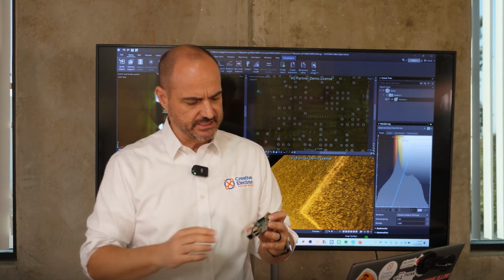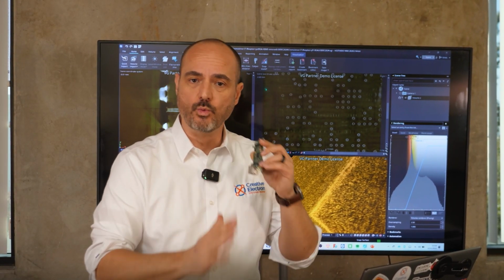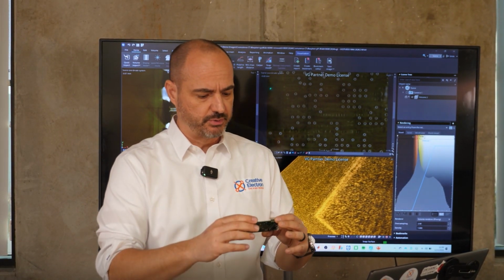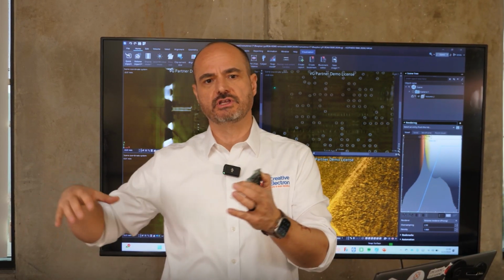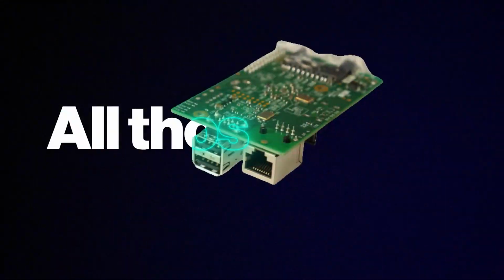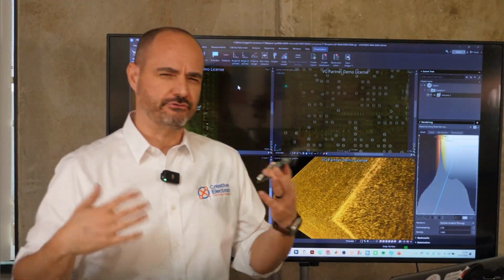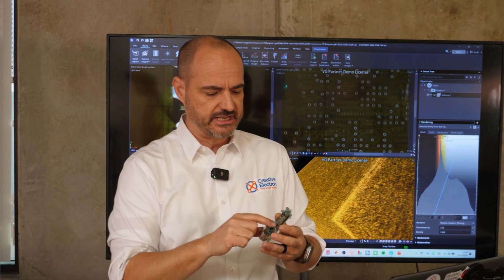In the past, destructive ways were used, right? So it means that you have to remove the component and then you literally have to physically sand one layer of the board at a time to expose the inner connection layers of the PCB, take photographs, and then use a scanner or some other technology to be able to piece all those layers together to recreate the circuitry. Or, as I said before, for forensics analysis, if you need to understand how to do a JTAG connection or power connection on a component, you'd have to use destructive methods.